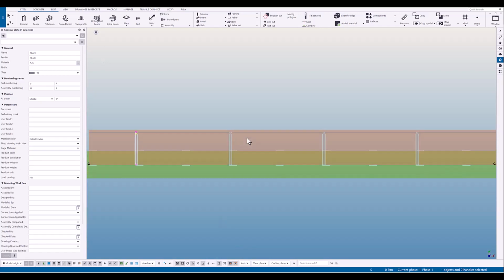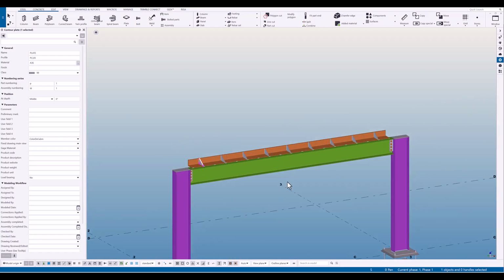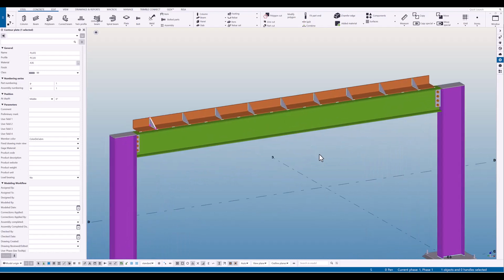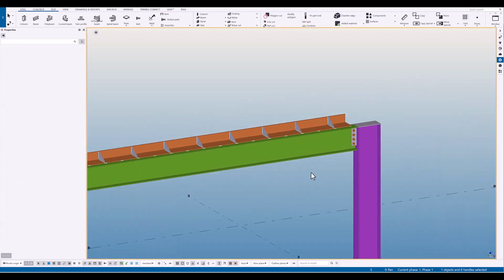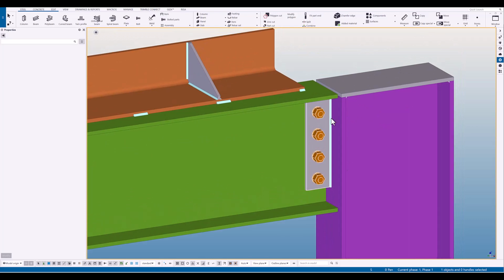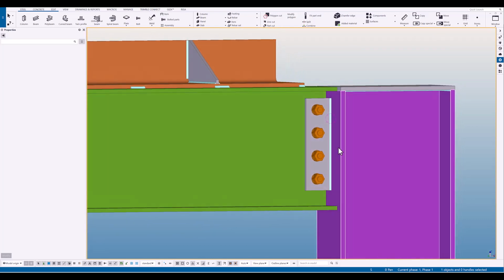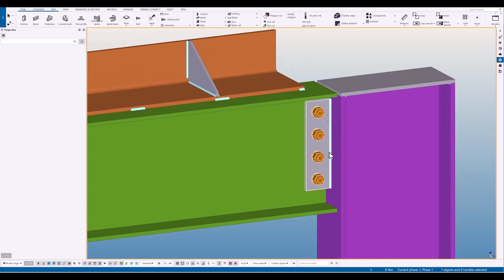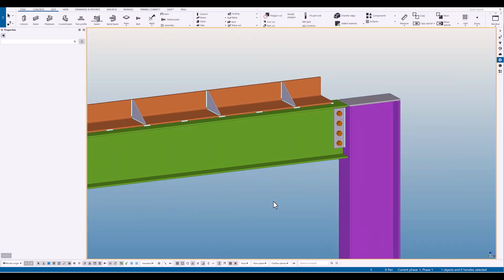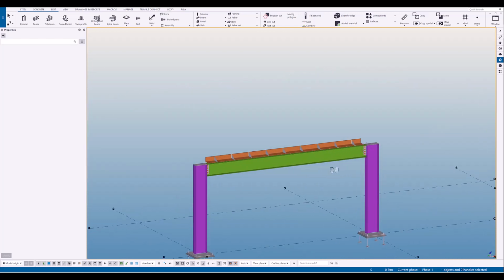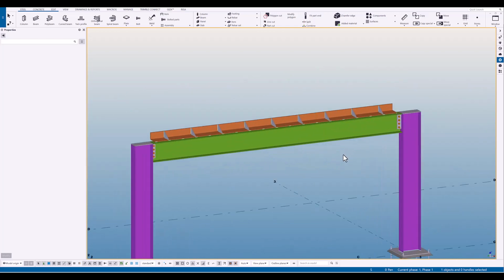Secondly, I want to talk about checking welds in the model and making sure they match the shop drawings. I have had success with this by checking the model welds using a yellow, or light-colored, highlighter on the contract drawings. When checking the shop drawing welds, I will re-highlight the same weld callouts on the contract drawings using a darker highlighter color. Orange works well for me. Of course, everyone is free to detail in whatever way is most efficient for them. This is just a suggestion that has worked out very well for me.